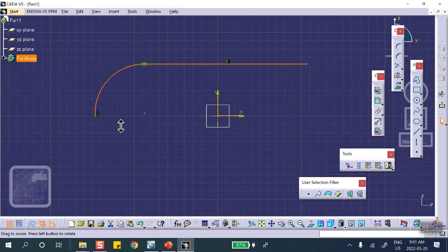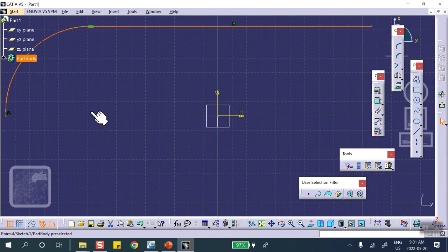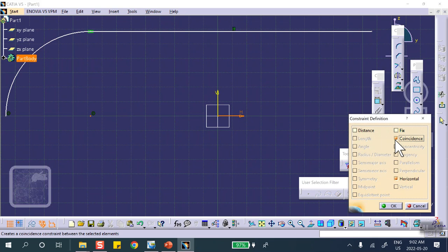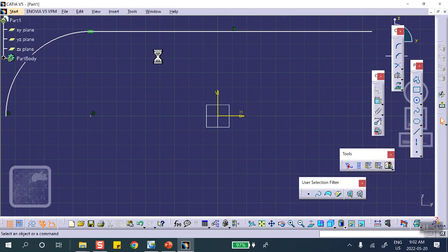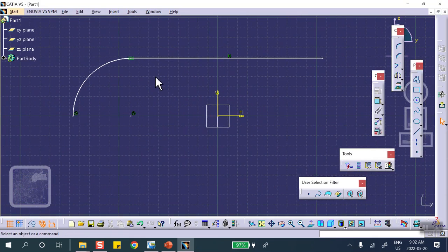Okay, this is also not cleaned up. Look at where the center is. It's not on that line. So I can select this, control that, make them coincident. Okay, now it's right. Ignoring dimensions. I'm not going to bother doing the bottom piece. You can if you want. Basically, you should mesh it later on.